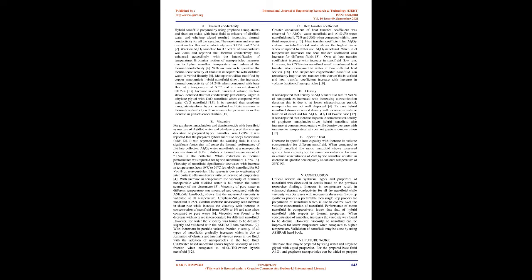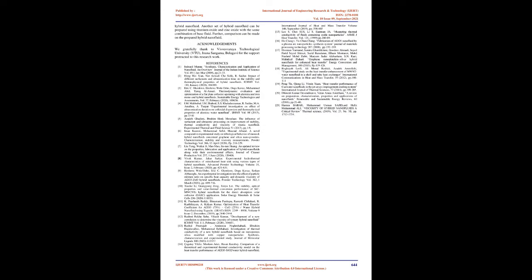9. With increment in particle volume fraction, viscosity of all types of nanofluids gradually increases, which is due to formation of clusters and internal viscous stress in the fluid with the addition of nanoparticles in the base fluid. CuO/water-based nanofluid shows the highest viscosity at each fraction when compared to Al2O3-TiO2/water hybrid nanofluid.